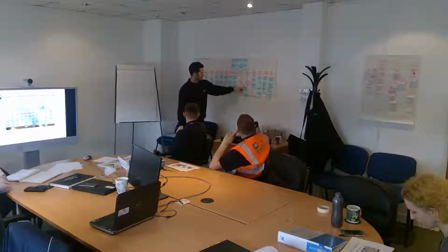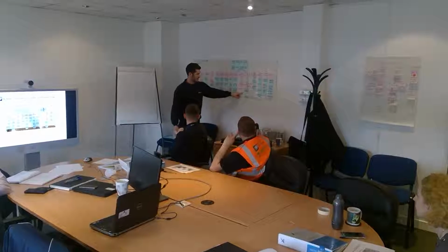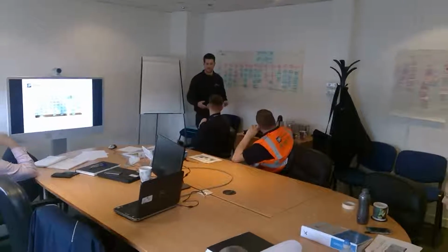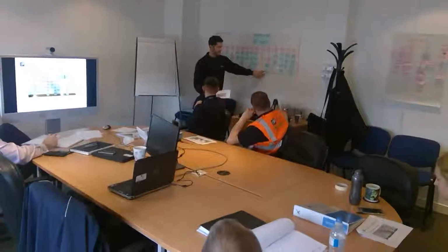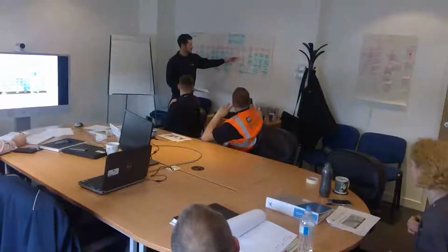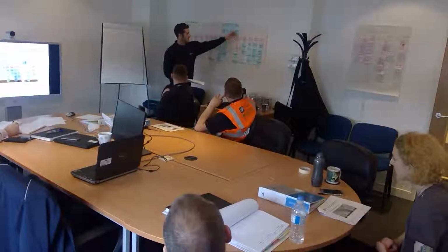Problems with weld inspection is availability of inspectors. They're sometimes busy, they can't get around in time, that has a knock-on effect on production, because the welder's stood doing nothing while he's waiting. An X-ray, an MPI, DPI could go down, obviously it's a failure, it needs reworking before it can get through.